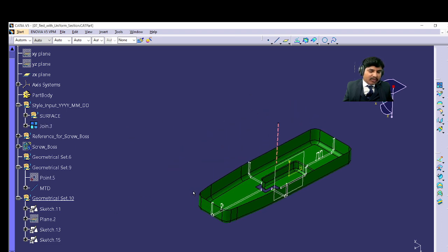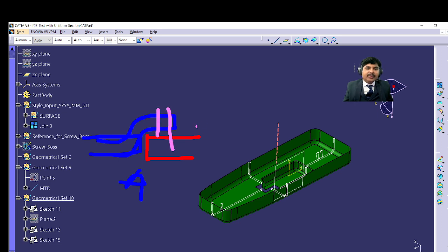Now if one more environment part is there, then we have to consider that if two parts are there in a plastic, then both parts are not just like this. You have to prepare one part having the overlap flange on the other, so there will be no rat hole. Here we have to maintain the gap and flush conditions depending upon the part, and then we will provide the features between these two on the hidden back sides.